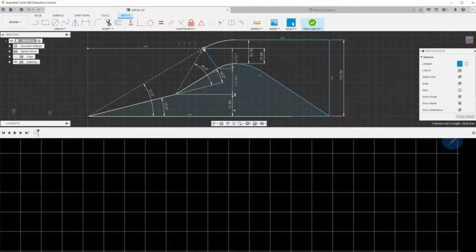And when you have this subsonic flow after the normal shock wave, as I told you last time, flow can be calculated analytically as isentropic flow because we don't have shock waves anymore. We neglect presence of the boundary layer. We neglect heat exchange with the wall. And we assume that flow is isentropic.